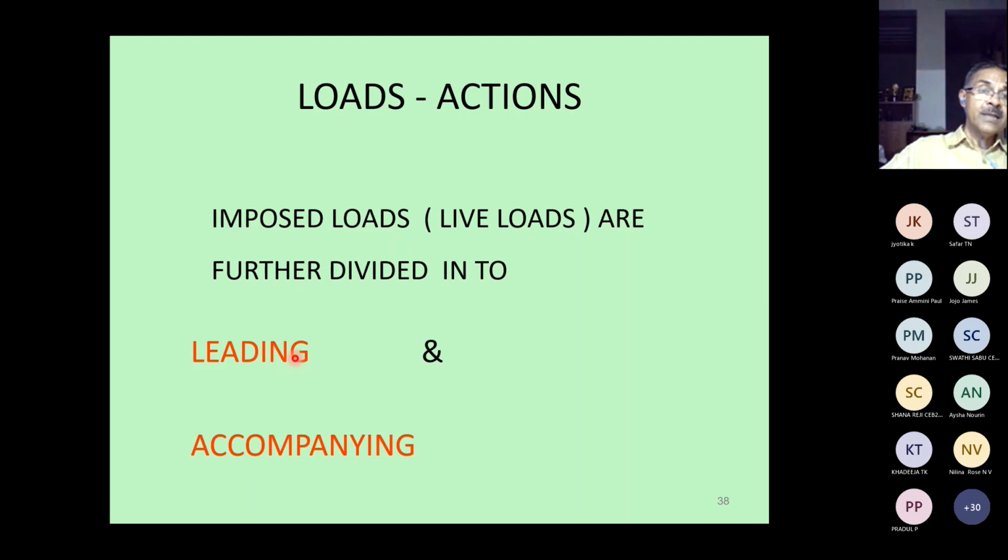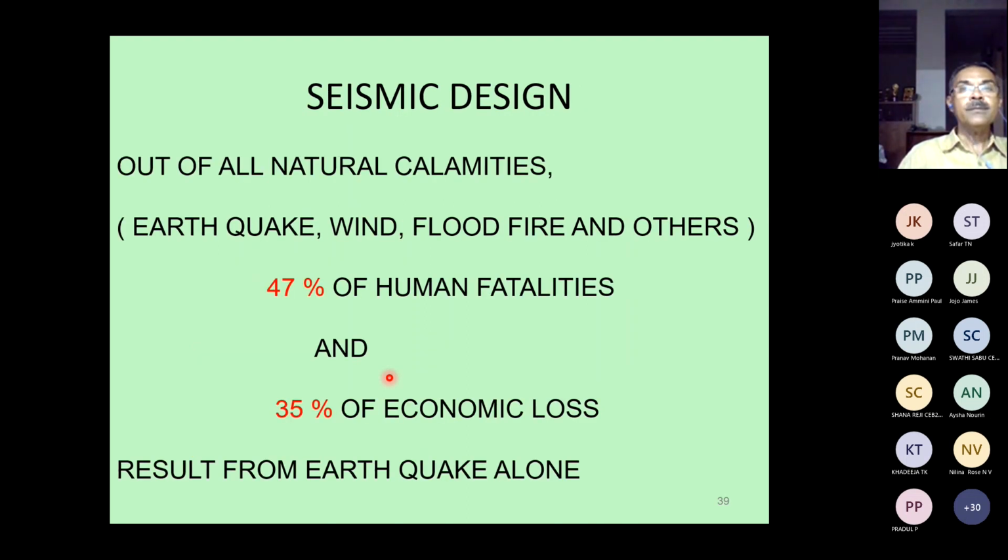So the difference is we put full factor of safety on the leading live load, but we put only a partial factor of safety on the accompanying live load. So the live loads, for the purpose of design, we divide them into leading and accompanying.